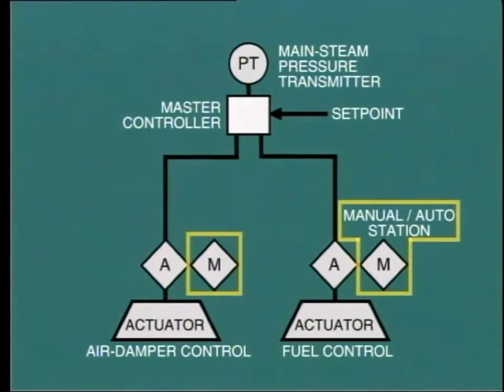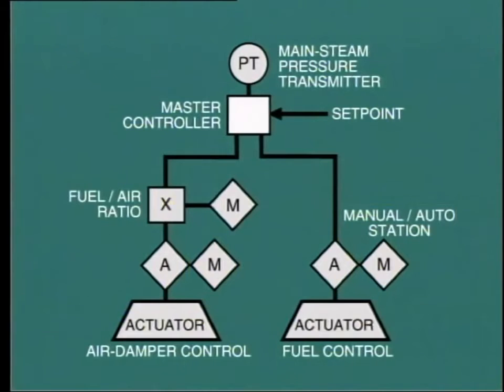Either of the actuators can be switched from automatic to manual operation if required. An additional control allows the operator to set the desired fuel-air ratio. Experience proves that more excess air is required at low loads to maintain stable combustion.